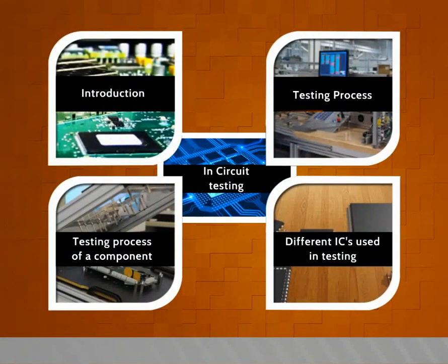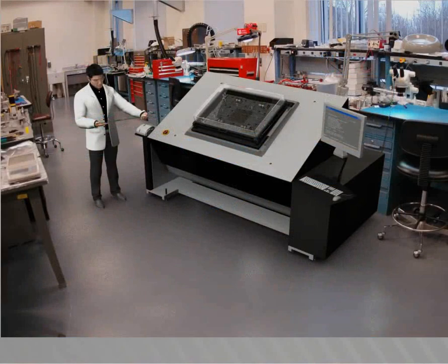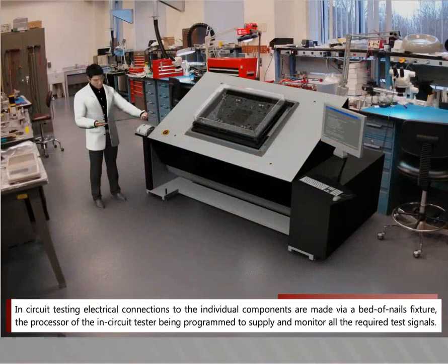Testing process. In-circuit testing, electrical connections to the individual components are made via a bed of nails fixture, the processor of the in-circuit tester being programmed to supply and monitor all the required test signals.